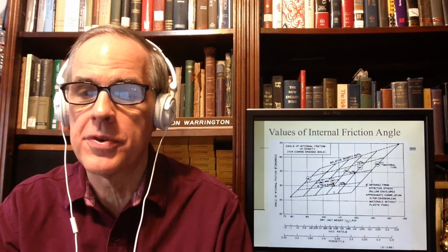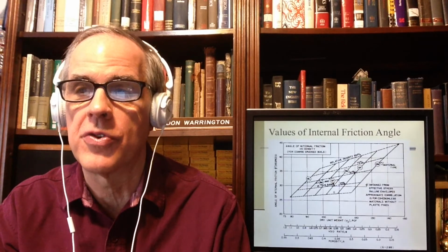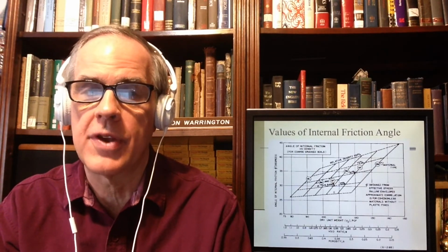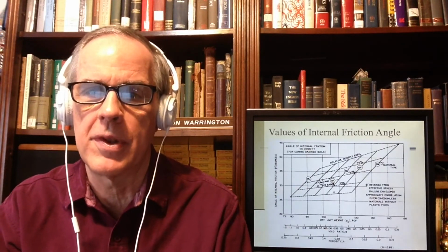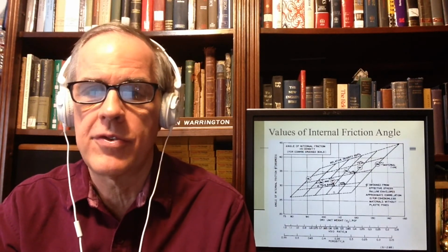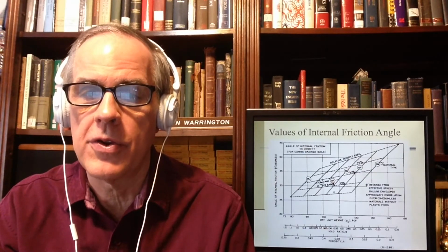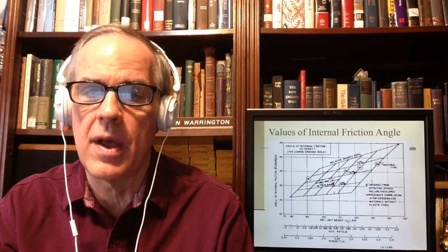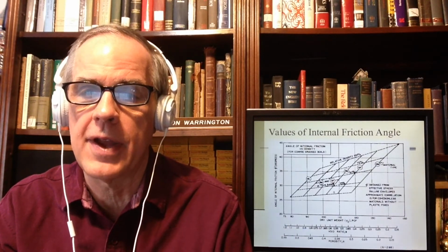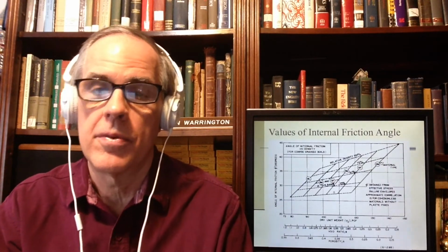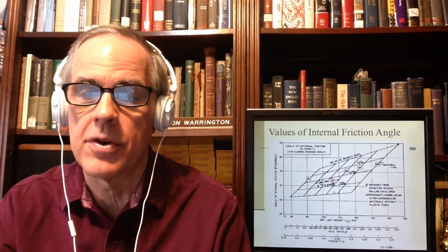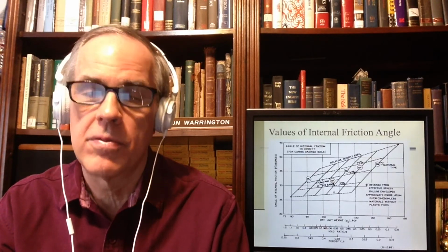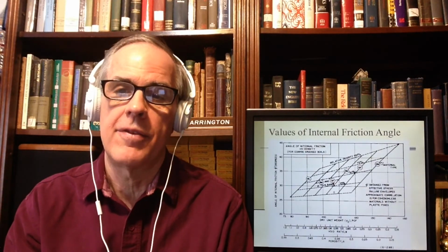This is a little bit more sophisticated for cohesionless soils. Your book has this chart in a little bit more legible form. And it shows the dry unit weight versus angle of internal friction for different classifications of soil. It shows you what you would expect in terms of the dry unit weight, relative density, and all that good stuff. So this is very handy to have as well.